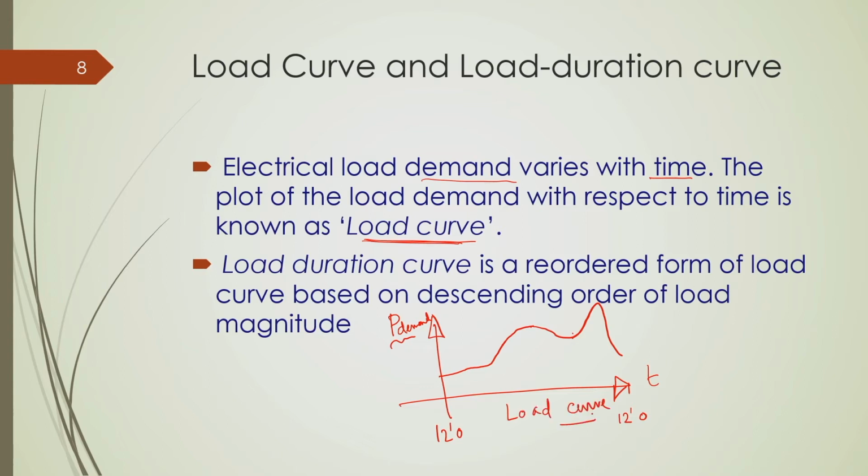Sometimes we plot this load curve with instantaneous power demand as I have shown, or sometimes we sample the overall time period at 15 minutes or 30 minutes. So, with 15-minute sampling, we take the average of demand during that time. If we sample like this, we take the average demand for each 15 minutes and then plot it.